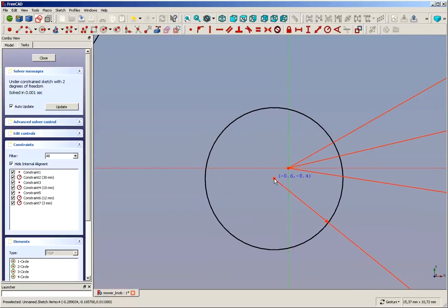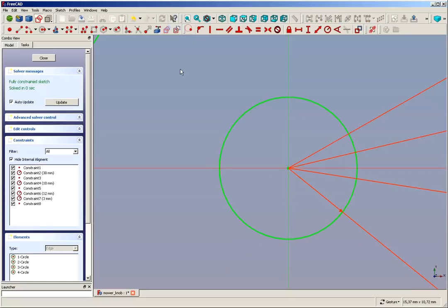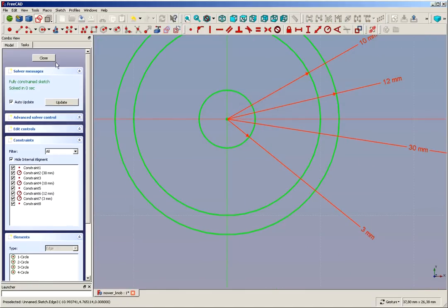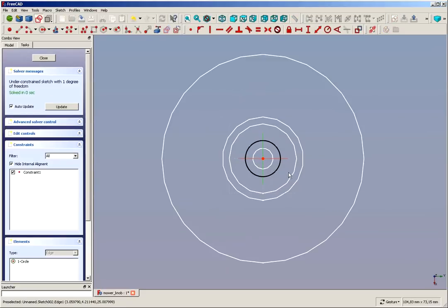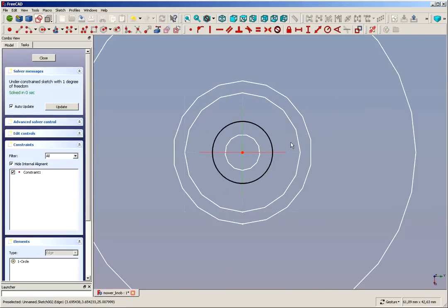That was the problem. I thought I centered it when I started drawing it, but many times this doesn't work. And then, unless you find yourself being very confident with your mouse and very precise, you better choose random positions and afterwards constrain it. That will make it easier to find errors later on.